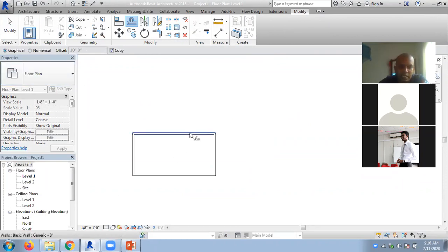Then go and select this wall. Say I selected the wall, but you see nothing happens now. It says click to enter offset starting point. Now I can't give a numerical value, so you have to give that value in terms of some graphical method. I selected this wall to offset, and say I want to offset something like this gap.